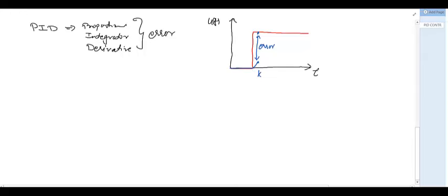So our controller will basically calculate the error, use that error to move close to the red line, and at every point it will calculate the error and try to get closer and closer and closer to the red line, and eventually it will reach a steady state. This is where our gain values for these controllers come into play. So if our gain values are correct or appropriate, then we can reduce the time it takes to get to the steady state and have less undershoot or overshoot.